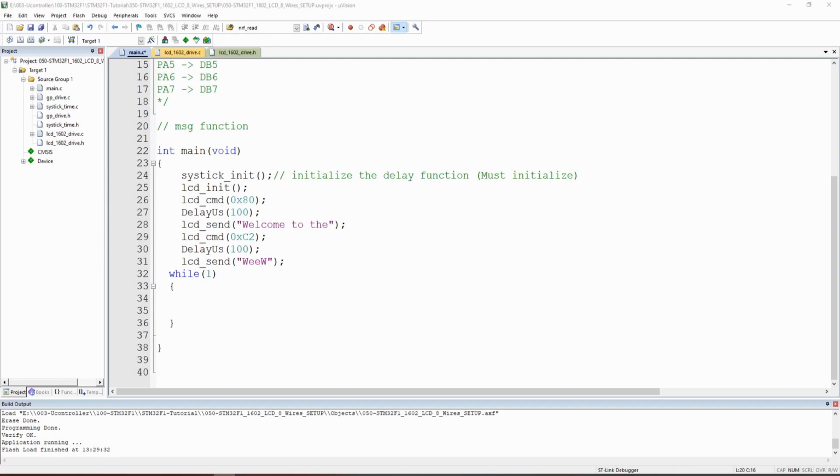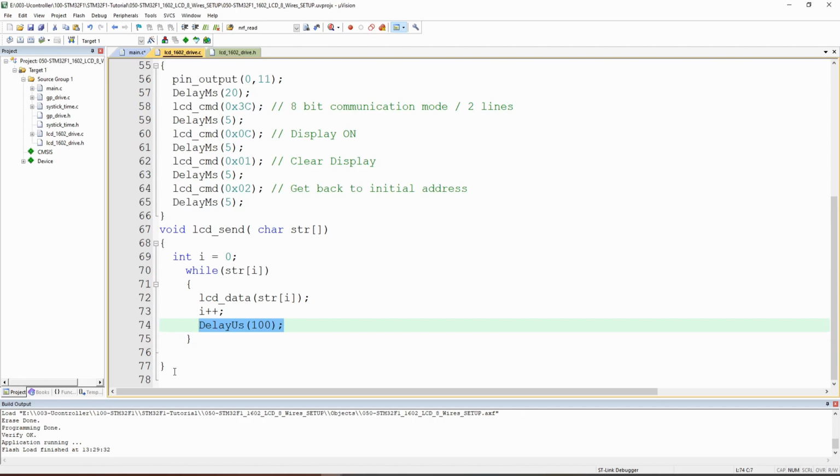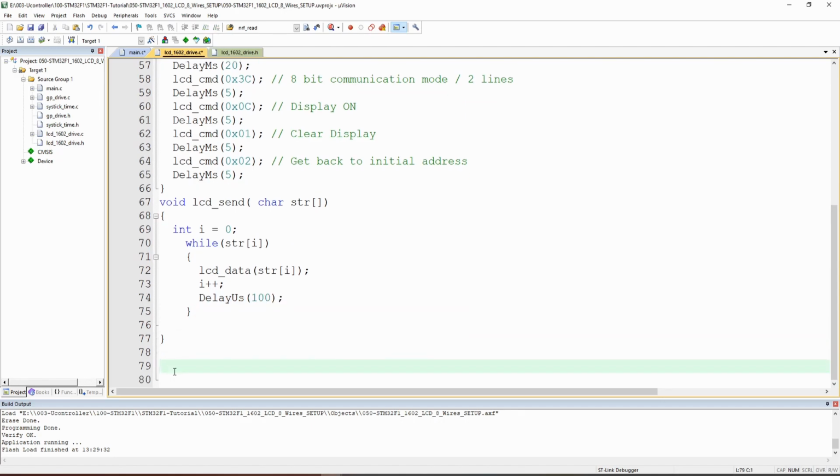Okay, we are finally at the third and final part of this tutorial, where we are going to summarize everything we have done in a function that will be quite simple and easy to use, like one line to make the display on the LCD. So instead of having all these lines to select the position, we are going to create a function that will summarize everything, and we call it LCD message. Okay, so let's start writing it.